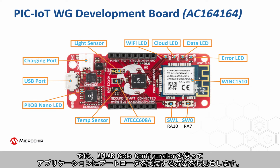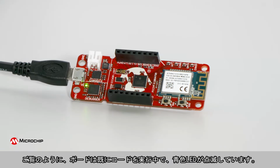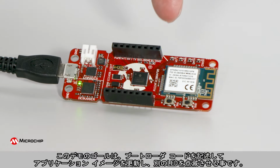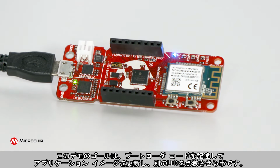Now, let's go through a quick demo on how to implement the bootloader in your application using MPLAB Code Configurator. For this demo, we will be using the PIC Wireless Google Development Board, and we'll be writing a bootloader code for the PIC24FJ128GA705 low-power MCU. As you can see, the board is already running a code blinking the blue LED. Our demo goal is to write a bootloader code and update the application image to blink a different LED.